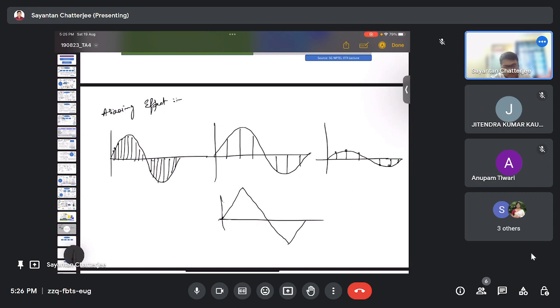To avoid this aliasing, anti-aliasing filters are placed in the PMUs. If some harmonic content is present in the signal but the sampling is not done at a faster rate, then the harmonics won't get captured and the signal would be reconstructed to some different waveform, which may represent a sinusoid or something different.